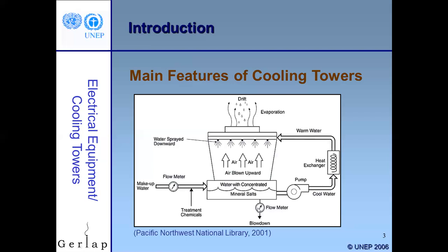We're showing a flow meter, which would be a best practice to actually measure the amount of blowdown flow. We are injecting some chemicals because it's fairly warm in the summertime. It can grow algae and all kinds of stuff that you don't want. And so we put some chemicals in here to keep that from happening. And we also want to meter the water flow to the tower. By tracking this over time, you can make sure that your tower is functioning properly.